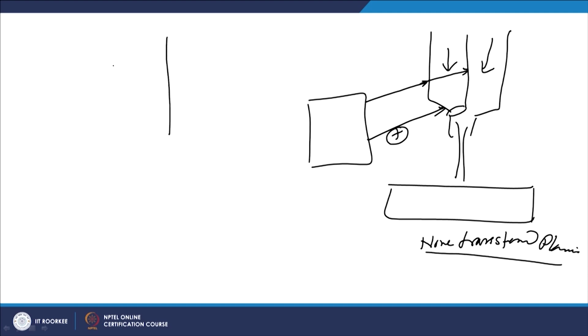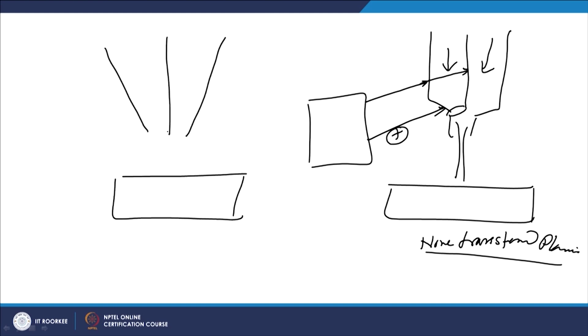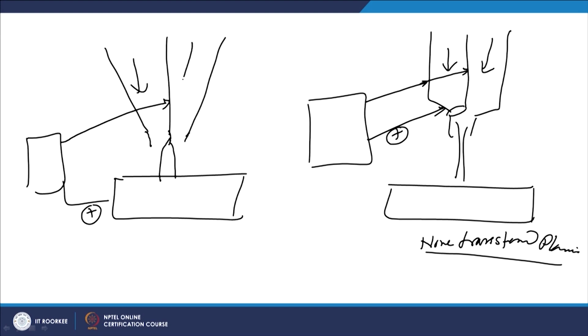In another case, the workpiece or substrate is very much part of the electric circuit. In this case the arc is struck between the electrode and the workpiece. Here the workpiece is connected to the positive terminal and the negative terminal is connected to the electrode, and the plasma forming gas is passed through, and whatever plasma is formed will be passed through the nozzle.